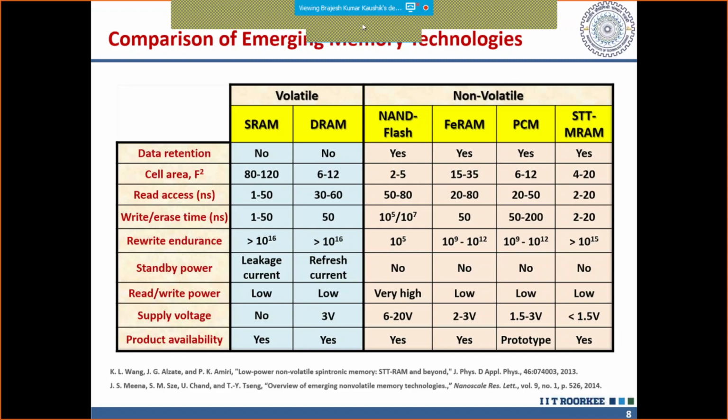All these things actually help us a lot when we try to make a choice among the different non-volatile memories which are available. Regarding rewrite endurance, I would especially like to mention NAND flash, which is very low in comparison to your SRAM and DRAM. And when you talk about STT-RAM, it has almost come to a comparable situation with that of your SRAM and DRAM. So this is really quite worth it in comparison to NAND flash or any other memories that are coming up.